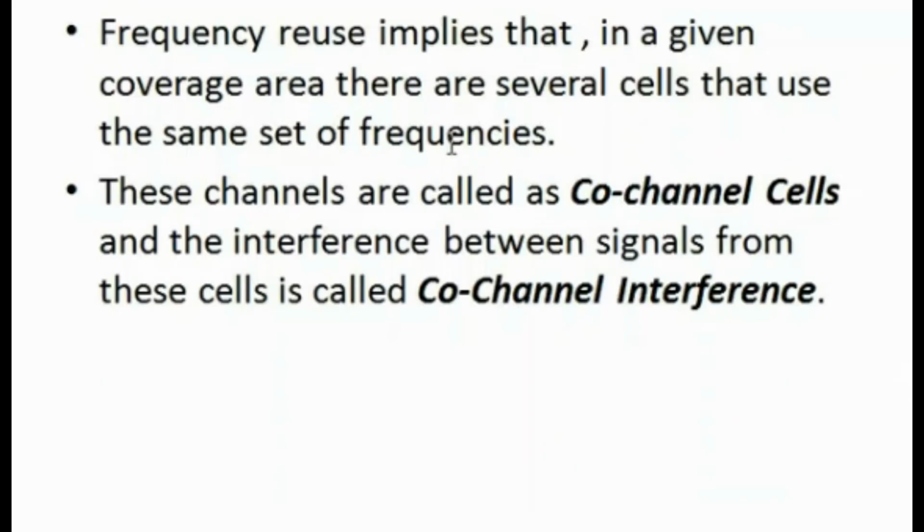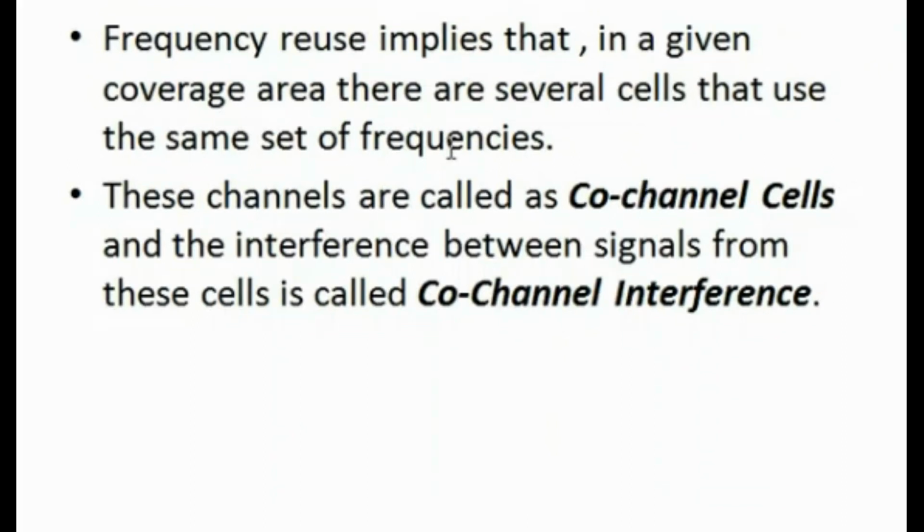Frequency reuse implies that in a given coverage area there are several cells that use the same set of frequencies. Since we have a limited frequency spectrum, the frequencies have to be reused. These cells are called co-channel cells, and the interference between signals from these cells is called co-channel interference. So we have covered all the basics.